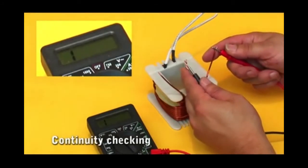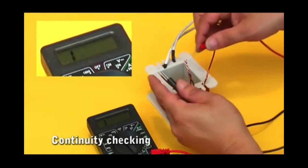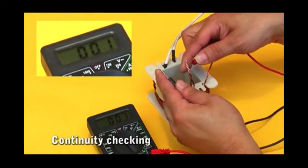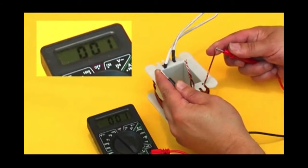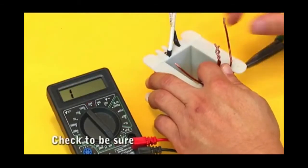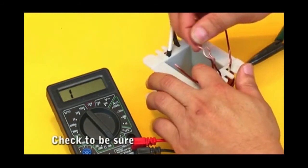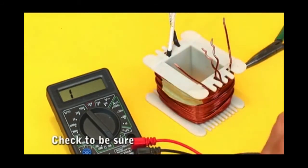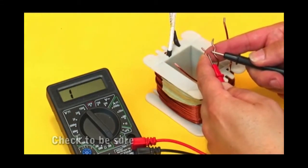Recheck continuity with the multimeter, which should show conduction between the three tips of the secondary winding. It is very important to be sure of the correct center point connection. For this we must remove two wires and remeasure. There should be continuity between the two wires.